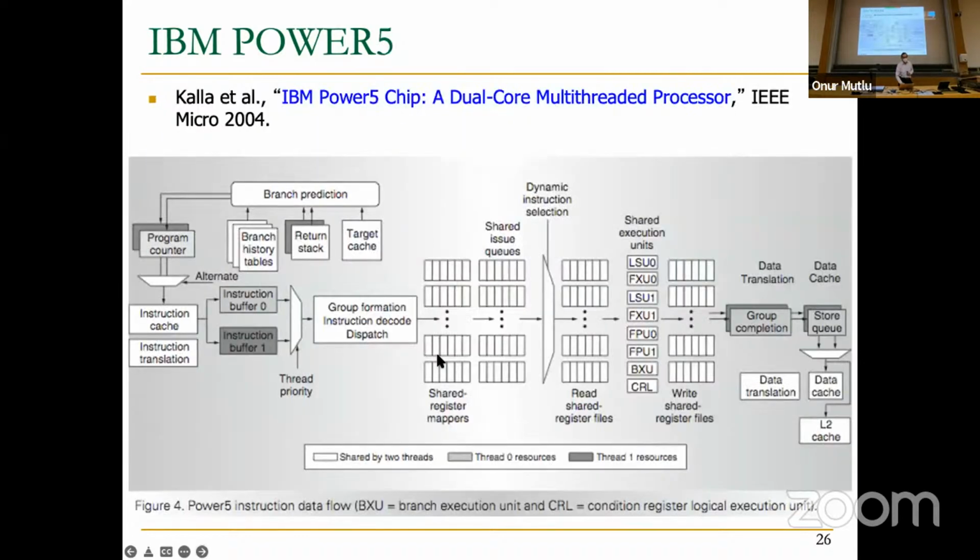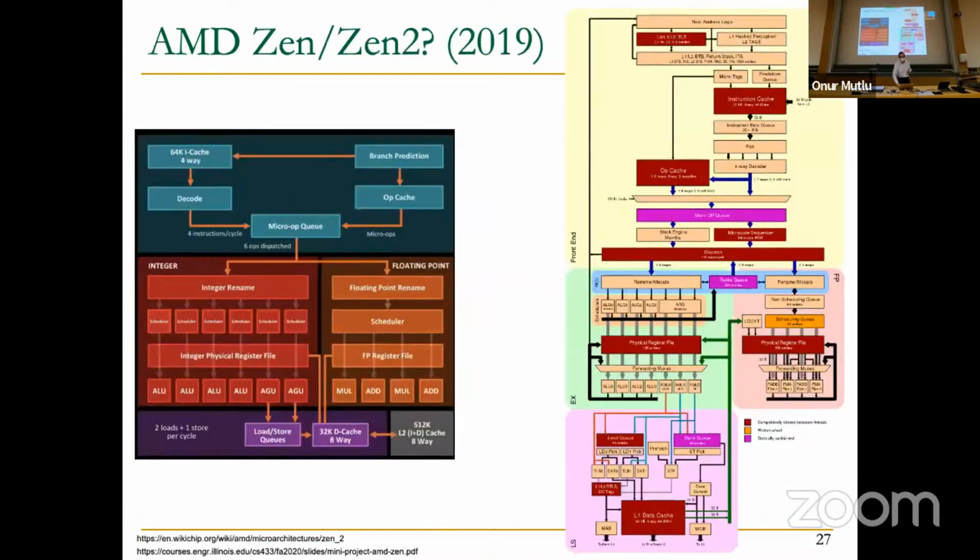And this is Power 5, which added multi-threading on top of it. So this has multi-threading in addition to out-of-order execution, and you can read about these. So these are some more recent processors. As you can see, the numbers have increased. If you can read this, I don't know if you can read this. So you can see the reorder buffer is 224. Physical register file is 180. I don't know if these are correct. That's why there's a question mark over here.